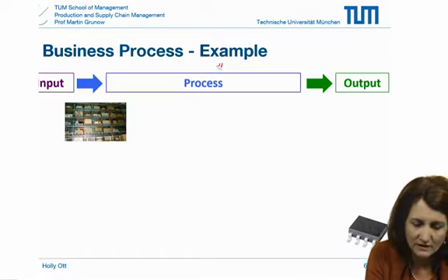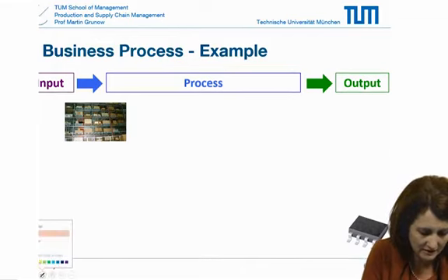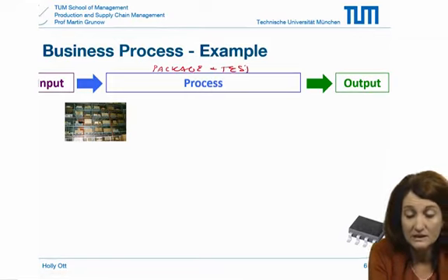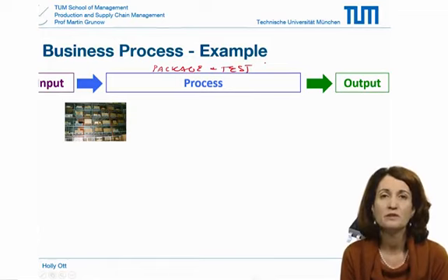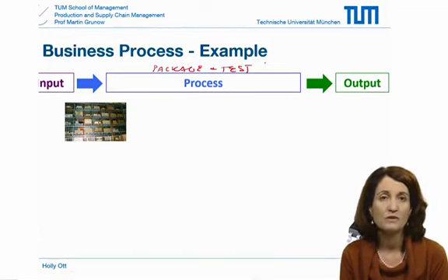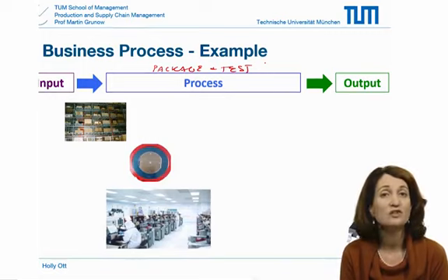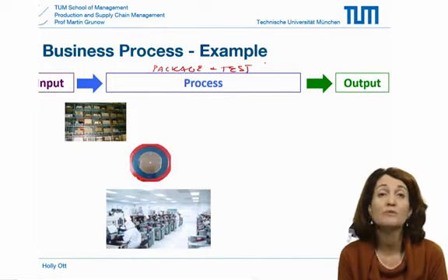We look here at the package test, and again, that takes several weeks. You start with the material wafer on the die bank. This is where the wafers are stored in a very, very clean environment. Then they need to be sawn up or diced into individual die and then attached to a substrate.